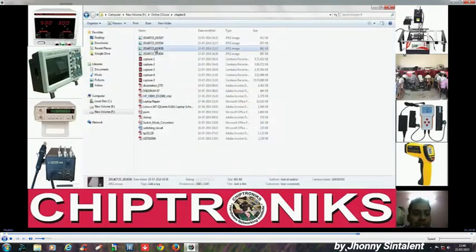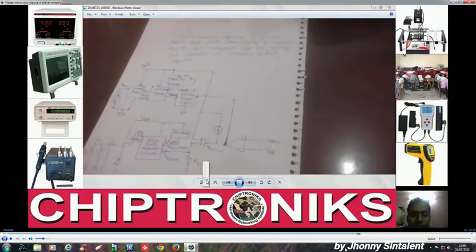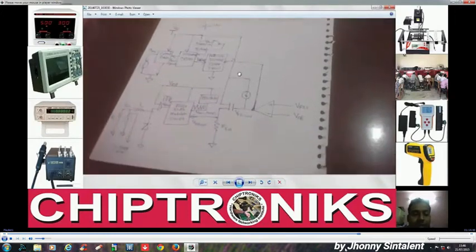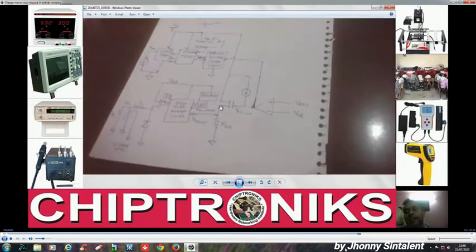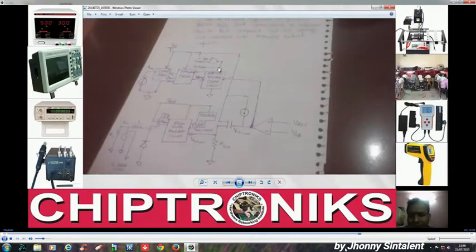And what is internal soft start? We'll see another picture over here, and this diagram is basically representing an internal soft start. Here we do not use any external capacitor, which will save assembling cost, right? And here what we have used is a current divider which is giving a lesser value over here, hence not producing that many pulses initially and saving this transistor.